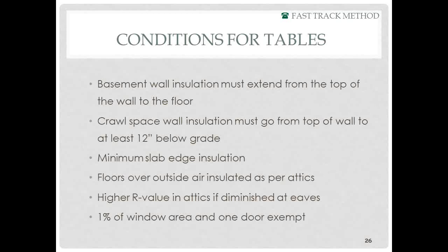For the tables, your basement wall insulation must go full height from the top of the wall to the floor. Now, you're allowed under the code to build differently than that, but there are no packages that cover that. So if you want to do something other than full height basement wall insulation, you'll probably need to go to the software or some other method.